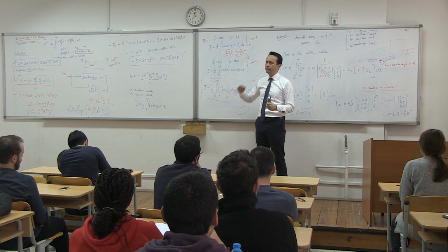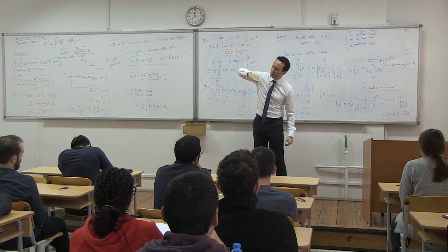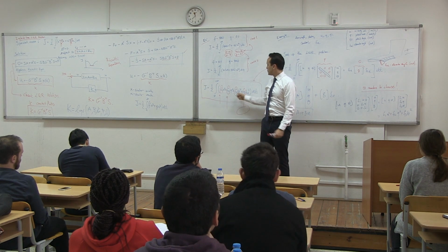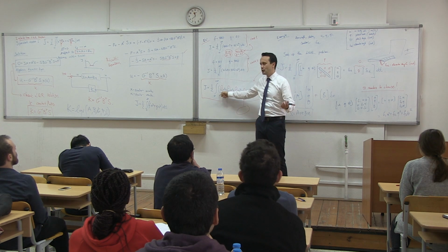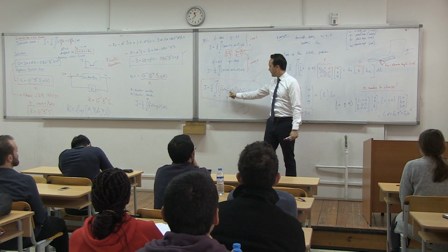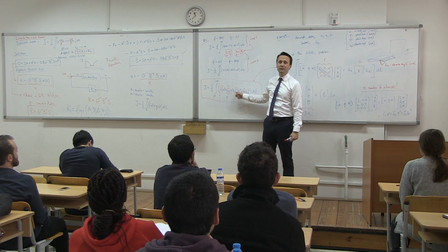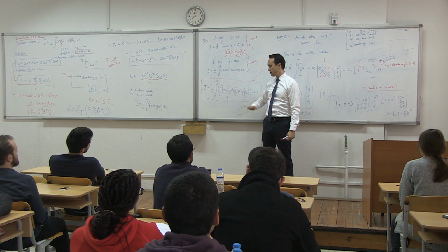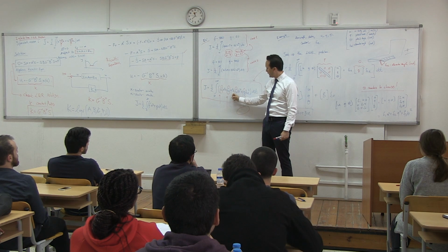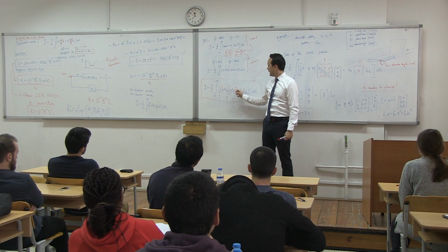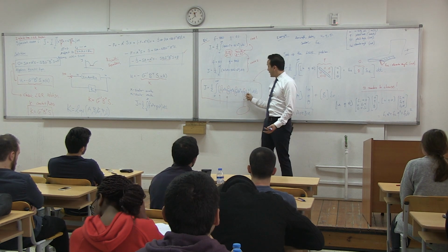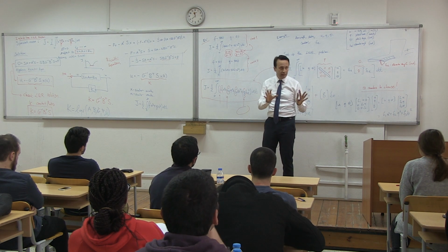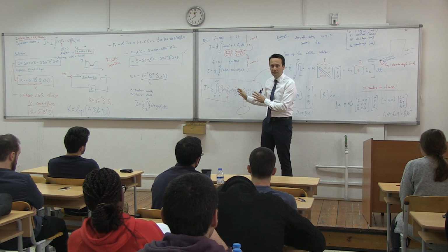I mean, how will U change the forward velocity of the airplane? If you put nose down, theta is large, Q is large, so you do this, then U will change. If you don't change these two too much, then this will not change anyway. So I would put a lot of emphasis on Q, not even on theta, because theta is also kind of changing slow. But Q, the rate, can change a lot. So I would put a lot of weight on Q, less weight on theta and U, and del E, I would probably make it comparable with Q. So that would be an intelligent way an aerospace engineer would handle this problem.